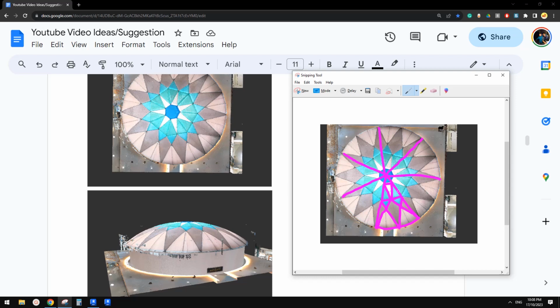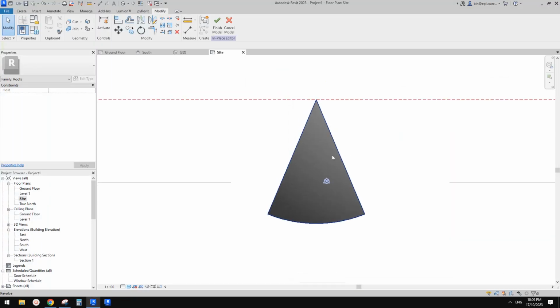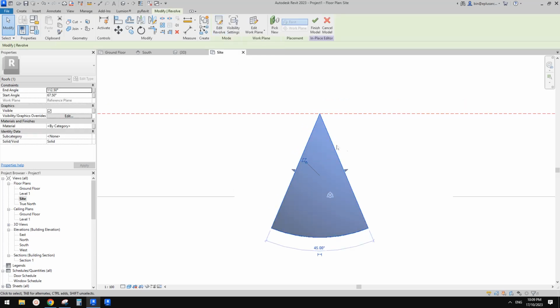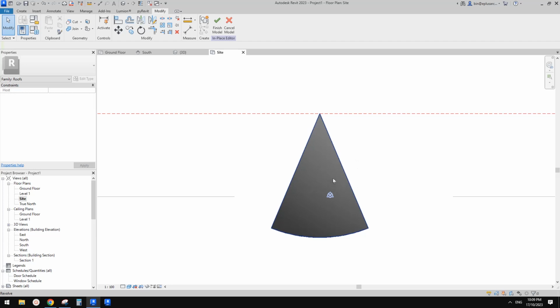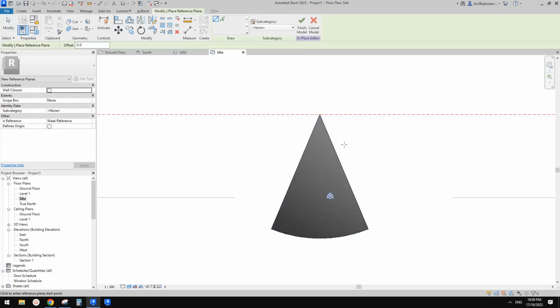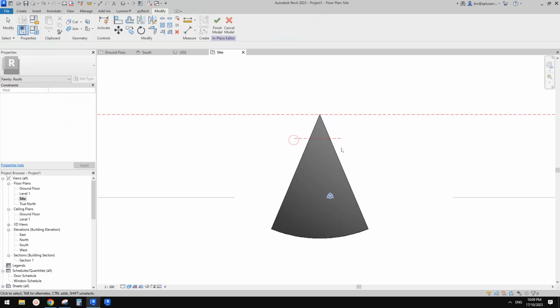So from here we can see roughly we can do one reference plane here, another one here. Basically we use the midpoint here, connect them, midpoint here, connect, and connect. So it's quite simple. Now we're going to use a reference plane. I'm currently in this model in place, the roof model, so that's fine. Let's just create a reference plane here.